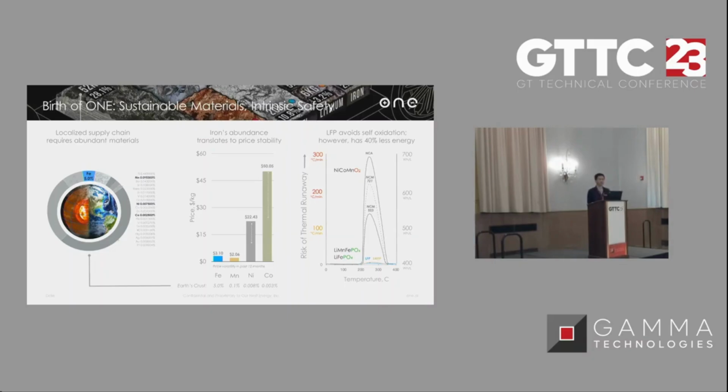As a result, their costs will be much higher than the iron-based cathode, which you can see in the middle figure. Another perspective, we are a little bit afraid of nickel and cobalt-based cathode is their chemical structure, which causes them to have self-heating effect during thermal runaway.